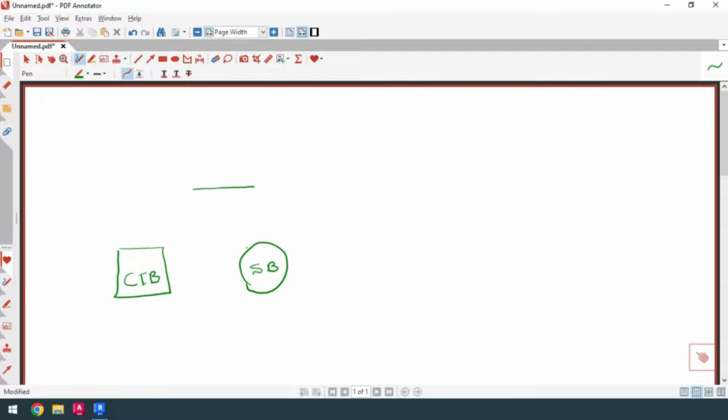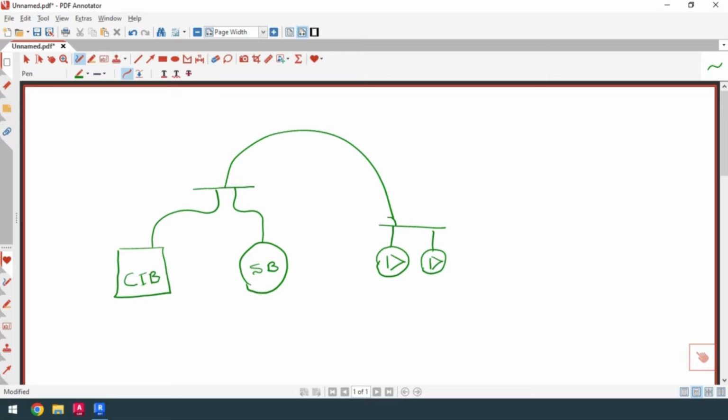If I have a collector here, I can get hot water from this boiler and also from this other boiler here. The hot water that is produced enters a set of pumps. I will show the pumps here. The pumps have a collector, and I send hot water into this collector here. Now from this collector, I have an input to the heat exchanger.